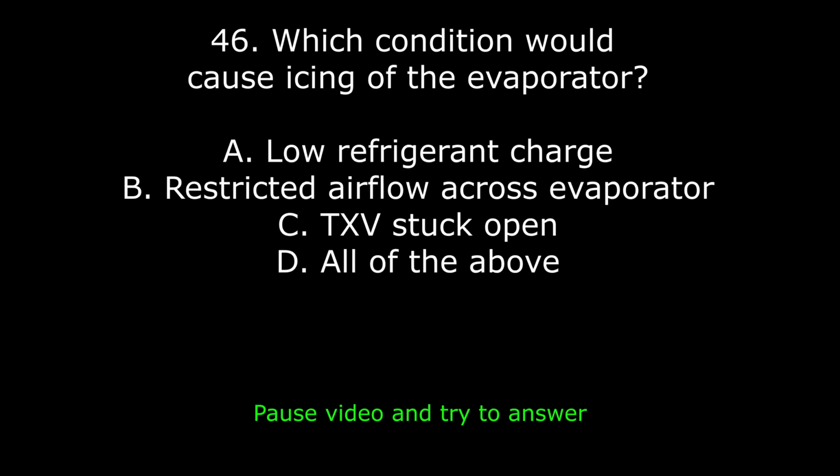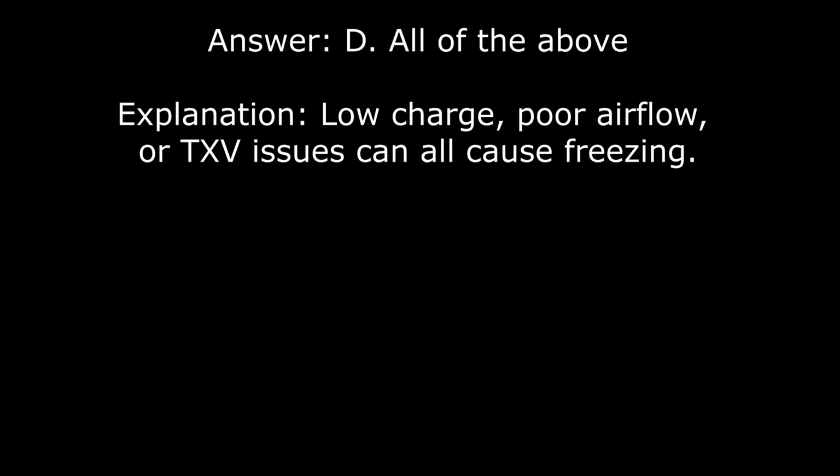46. Which condition would cause icing of the evaporator? A. Low refrigerant charge. B. Restricted airflow across the evaporator. C. TXV stuck open. Or D. All of the above. Answer: D, all of the above. Explanation: low charge, poor airflow, or TXV issues can all cause freezing.